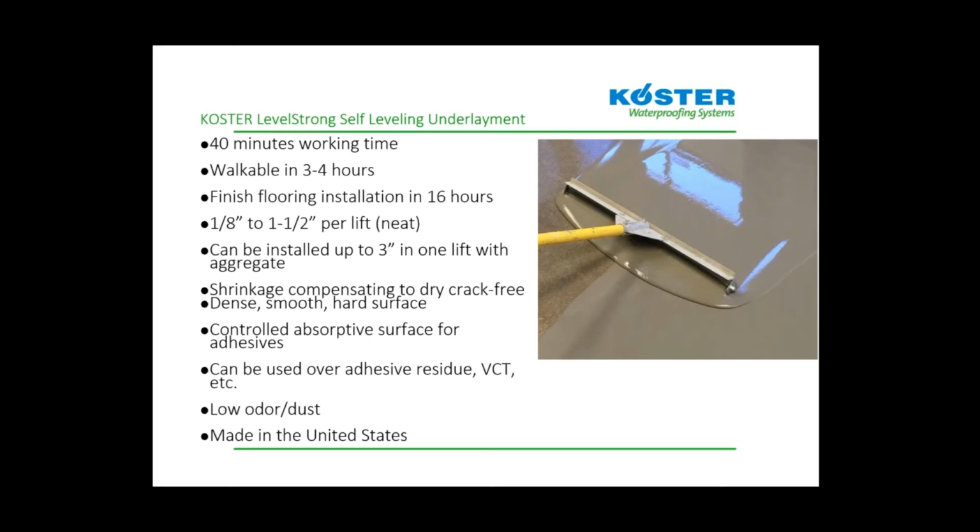It can be installed in layers between 1/8 to 1.5 inches per layer, or per lift, neat with no aggregate. When used with aggregate, it can be used up to 3 inches per layer. The next slide is going to discuss how we do that with aggregate.